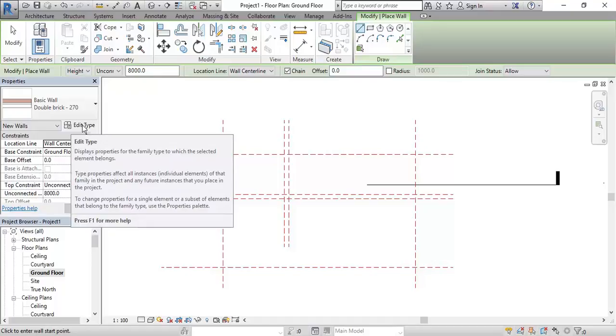And that's really important. You've got to do that for construction, as you'll see later. And just think about the sort of work you'll be doing. For decoration, almost every job will involve existing elements. In fact, I can't think of one that wouldn't. And so you're going to draw most of those things with this style, with basically a thin line and a black hatch. And then you only show material hatches for new things.